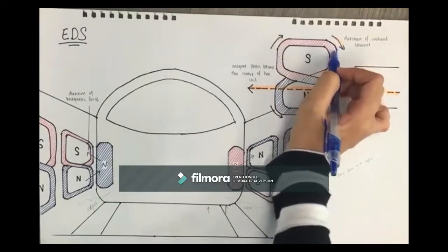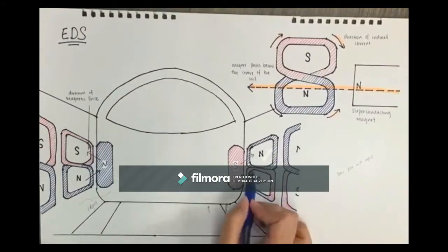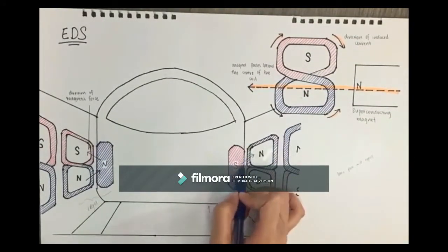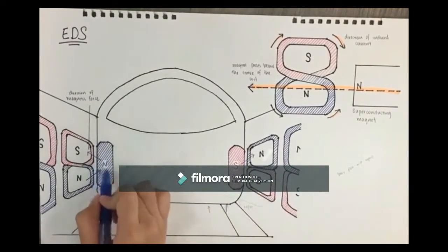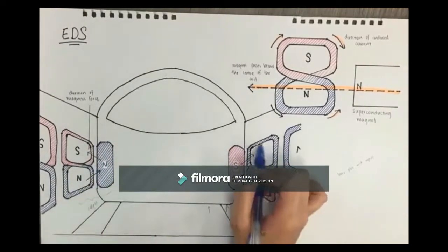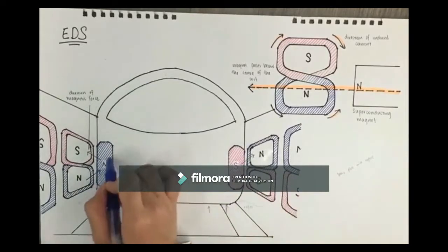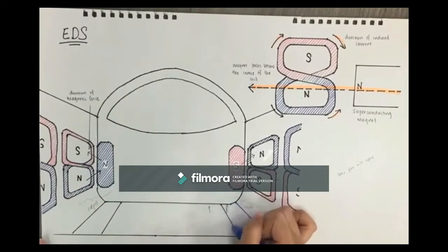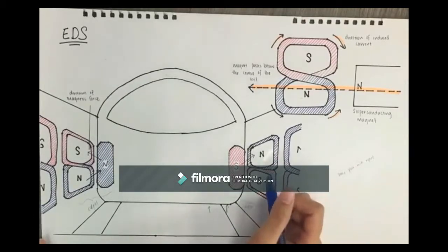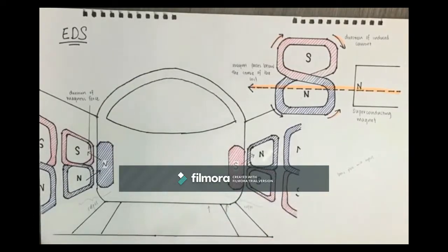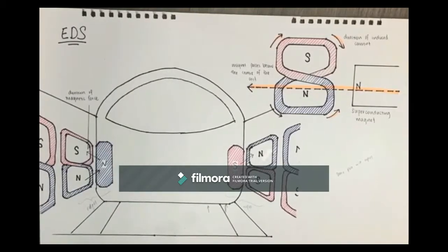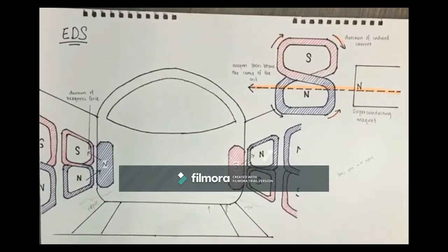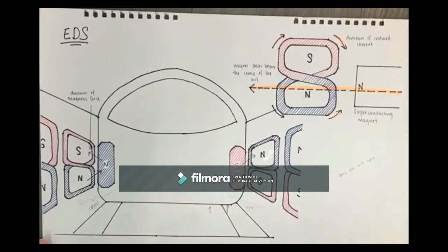The magnetic pole in the lower half of the H-shaped coils is the same as that of the superconducting magnet, while the upper half has the exact opposite of it, so that both halves of the coils generate an outward component of magnetic force on the superconducting magnet and levitates the train. Since the H-shaped coils can induce a current and generate magnetism only when the superconducting magnets are in motion, the train cannot be levitated when it is at rest.